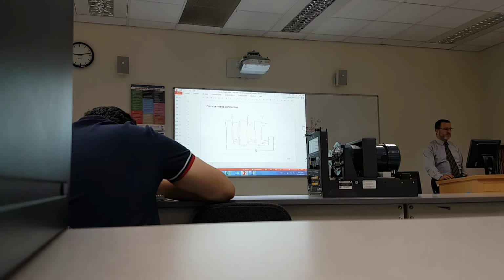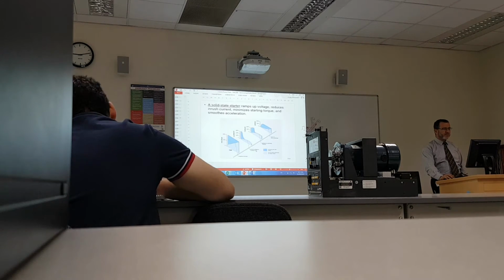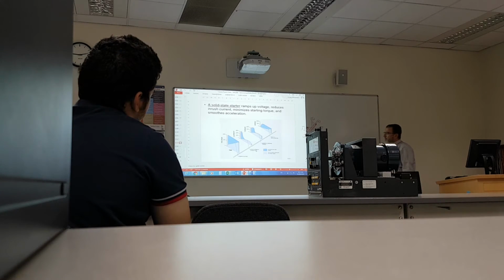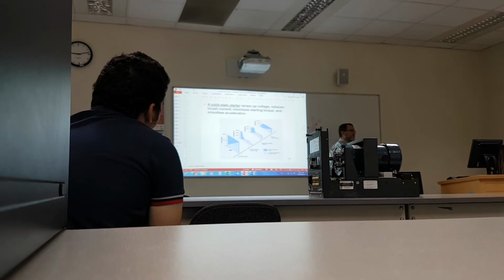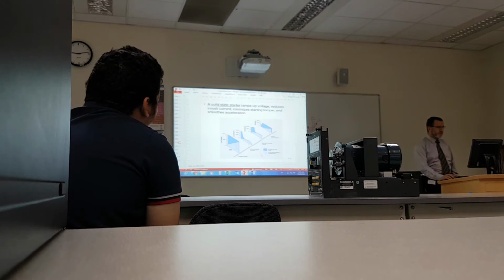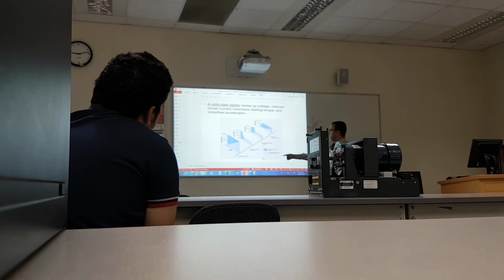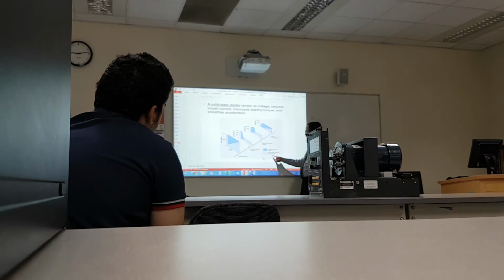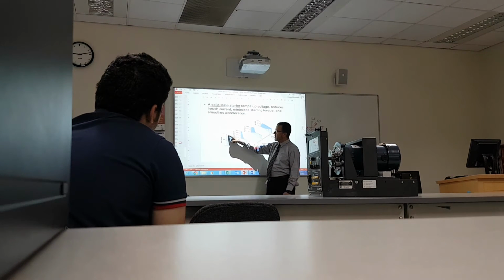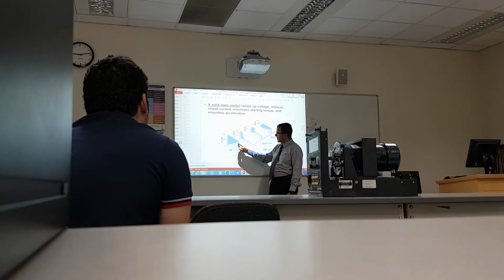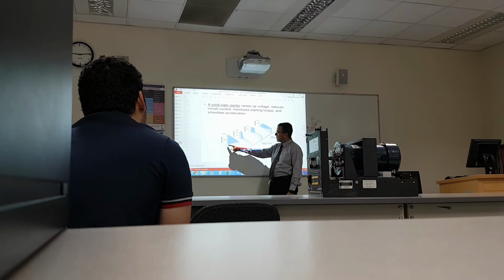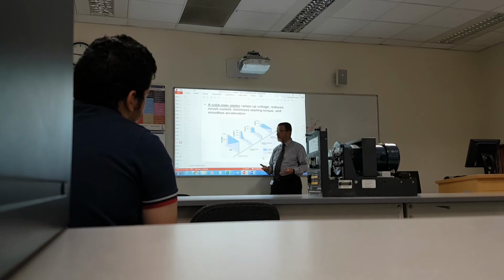Okay, and we'll talk about these control circuits. And why delta? This is the one that we did not really cover. This is the solid state starter. So this now gets into computer chips and all that stuff. It shows you here, this is across the line or direct online starting, and this is solid state reduced voltage starting. The voltage is at 100% with direct online, but with solid state, the voltage is increased over time. It starts much lower, so it applies reduced voltage.